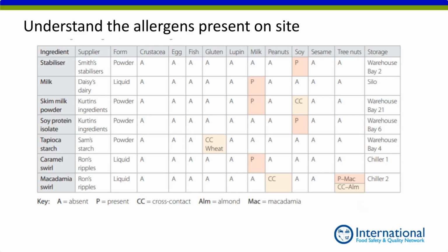So you can do the same type of zoning you did for the microbiological hazards. You can do the zoning for the allergen potential. So if you have 3, 5 production lines, and you have some kind of allergen on one line, and on the second line you don't have it, you can say this is zone 1 where I have this type of allergens, this is zone 2 where I have this type of allergens, etc. And then you really evaluate where contamination or cross contact can happen.